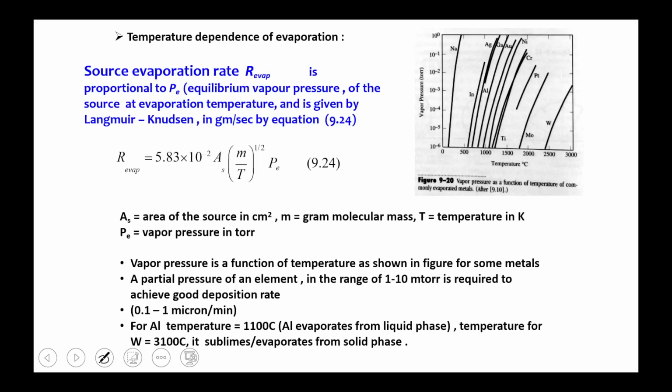So this is the temperature dependence. So we can put the temperature to the substrate also in that PVD. We have the filament there, and when your sample is held, there is a filament. We can heat that substrate also, and it will be easier for stacking of the material. When it is heated, it will be easy to stack a larger number of atoms on the surface. It will provide more sites to condense the atoms on the surface of the substrate when we heat the substrate.